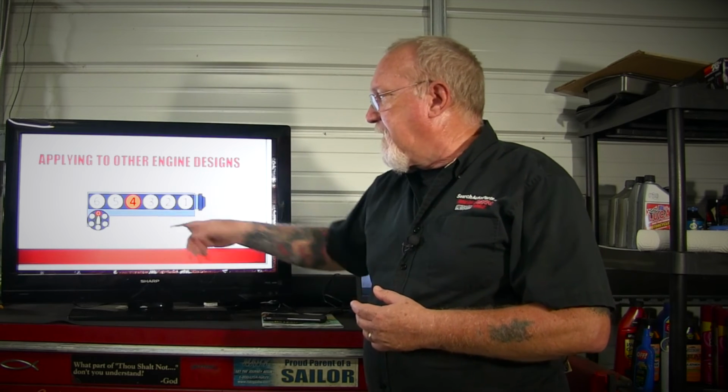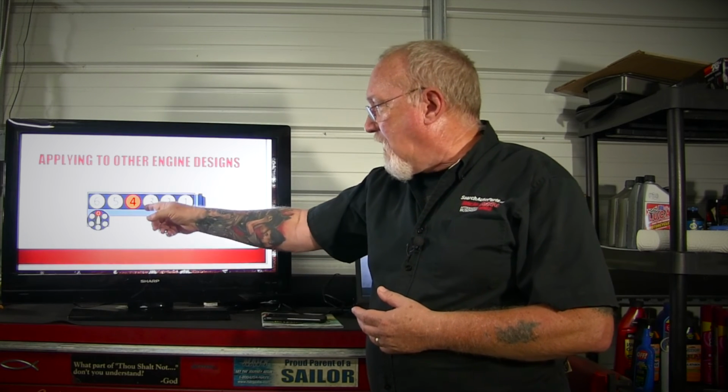So what would happen if number 4 had no fuel? What kind of loss, or what kind of numbers would I expect to see there? Well, 1 out of 3, that's 33%. So now I may see total fuel corrections way up there. On a 4-cylinder, you're probably not going to see them anywhere near that high because that's way outside of the specs. You may just see a system lean code set along with the misfire.